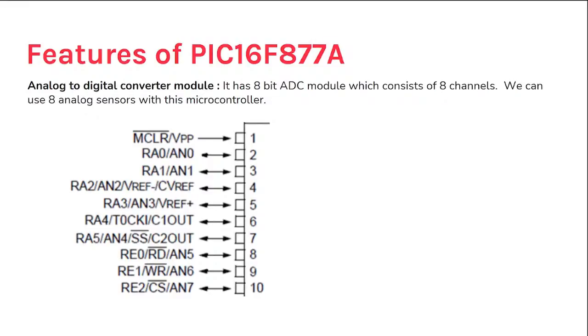It has an 8-bit ADC module. These are the pins from 1 to 10. It has 8 channels: AN0, AN1, AN2, AN3, AN4, AN5, AN6, AN7. These are the pins which can accept analog inputs. You could directly connect an analog temperature sensor to these pins.